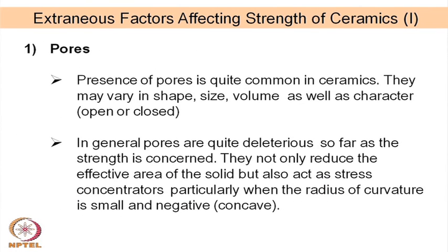Well, that is all so far as the concept of Weibull modulus is concerned. Basically, we wanted to say that the Weibull modulus must be high enough so that the reliability of the data is much better, and we have a better material to be used for the actual applications, right. So, that is also an indication of how reliable that material will be for any technological or structural applications.